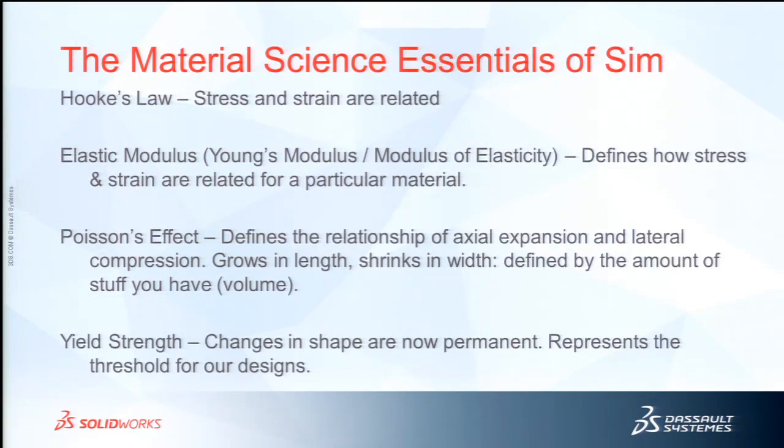The elastic modulus defines the slope of the line, right? We're going up this straight line on that stress-strain curve. The elastic modulus, or Young's modulus, or the modulus of elasticity, defines how stress and strain are related for a particular material. You need to know that.